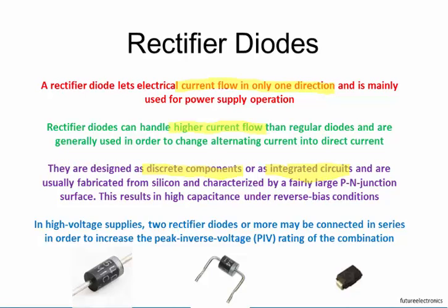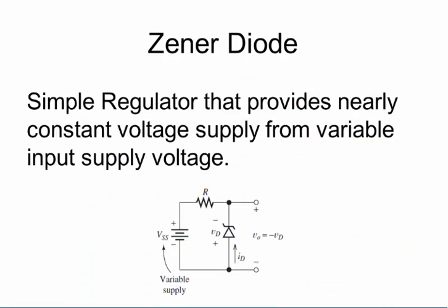We have 6 diodes packed into a very large module, designed to be mounted to a heat sink with thermal paste in between. So these are the different packages that you find them in. This one on the left is just a generic diode with a slightly higher power rating. It's the same as the one in the center diagram, and the one on the right is a surface mount device, also a rectifier diode.